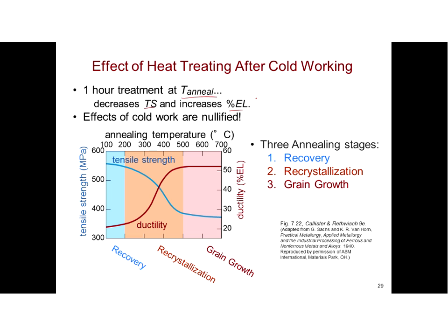The question was, does the material recover its original percent ductility? And the answer is yes, nearly. If it was a pure sample before, like a nearly single crystalline material, it should have roughly the same ductility. So what happens is the effects of the cold work are nullified. The sample returns to its original state. Well, we'll look at what happens with the number of crystals.